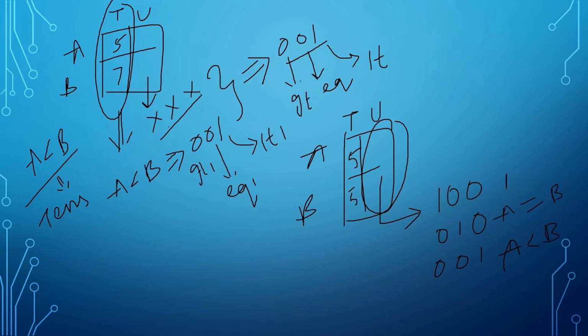Why I am saying all this? You will get a question like this, right? Before, we discussed only a one bit comparator. Now if you want to compare two inputs, each of which are 3 bits or 2 bits or 4 bits, then how to compare? What process do we need to follow? The process we need to follow is the same process we have discussed before for tens and units place. The same we have to follow in binary numbers also.